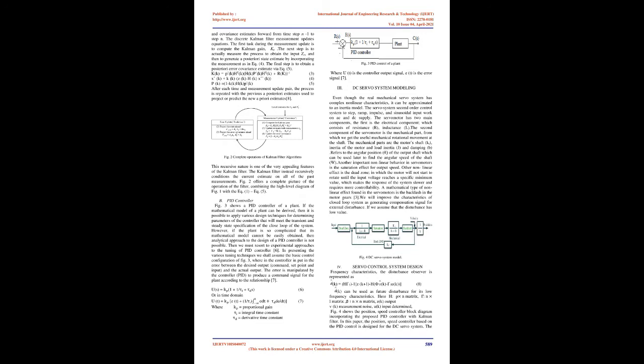Kalman filter can be applied to a dynamic system that involves random perturbations, and gives a linear, unbiased, and minimum error variance recursive algorithm to estimate the unknown states optimally. In this paper, we propose a Kalman filter algorithm to estimate one step ahead states and disturbance. Therefore, we can improve the performance of estimation for position and speed. Also, compensate disturbance, which improves the characteristics of servo control system.